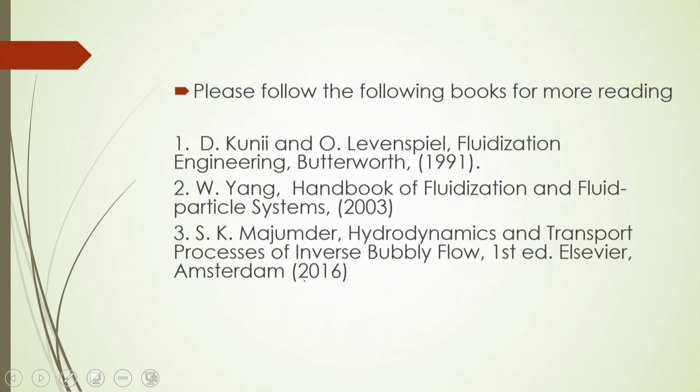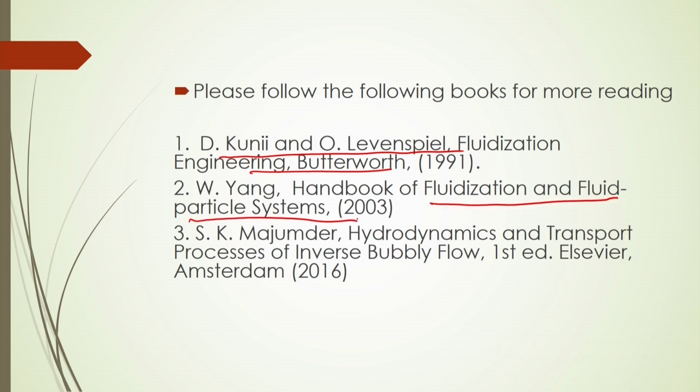So, you can calculate this phi SL here. For more details on the different frictional pressure drop analyses and predictions from your experimental data, you can follow the Cooney and Levenspiel books, and also the book Fluidization and Fluid Particle Systems by Young, 2000.